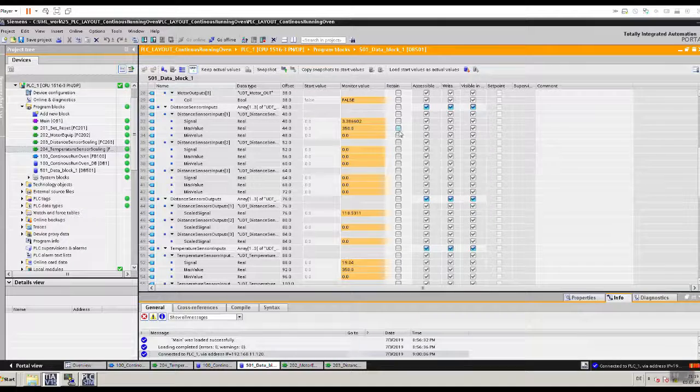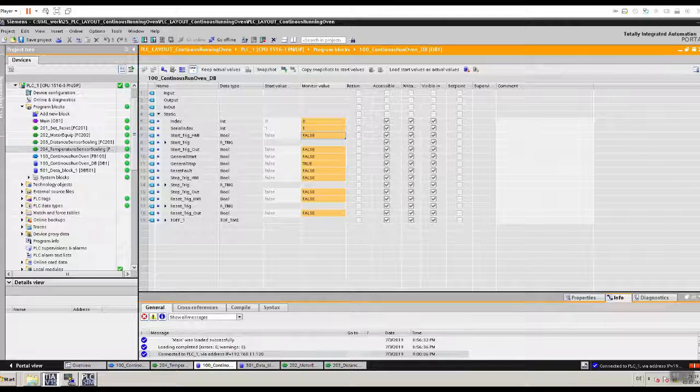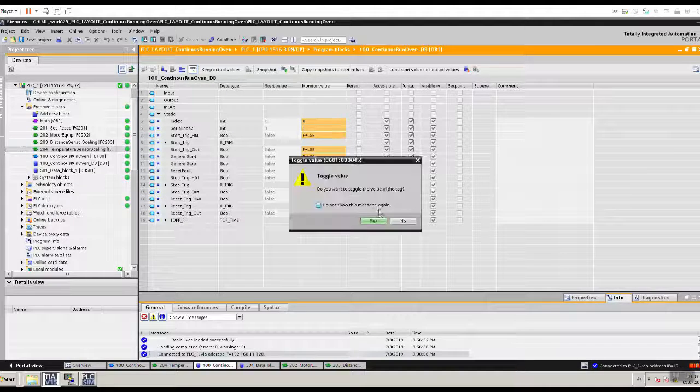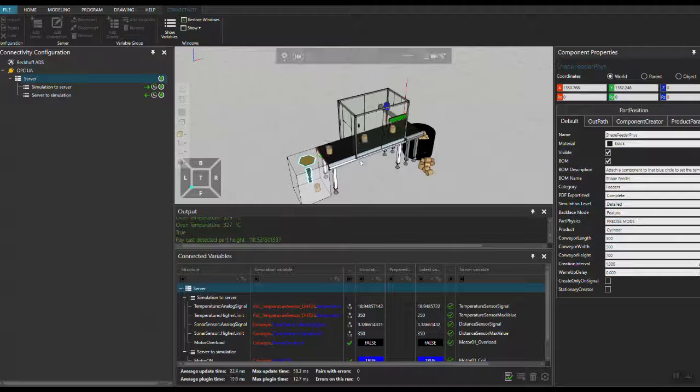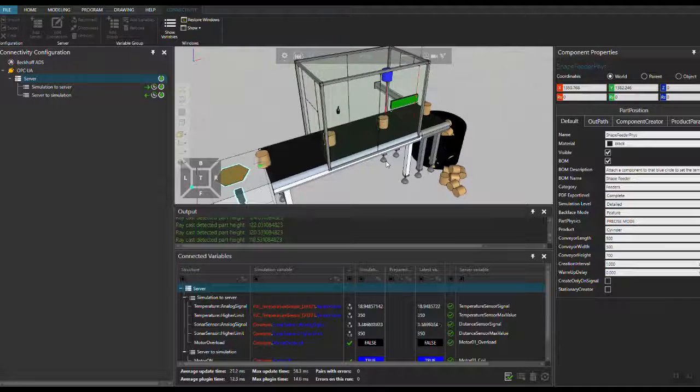Okay, so he needs to do it this way: let's go here and reset trigger from HMI, yes, and then yes, and then general stop, and then start trigger from HMI again, and then general start is on again. So it's turning, and then the oven is running again until it gets a value less than 320, or an overload signal happens.